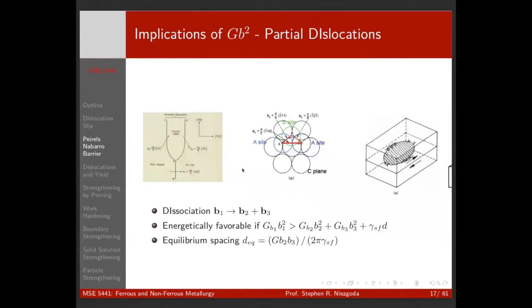And that's basically that dislocations in real metals never look like the regular perfect edge or screw dislocations that we talk about. Typically, they're dissociated, right, into partials. And we won't get much into the structure of those partials except when we talk about nickel superalloys towards the end of the semester.